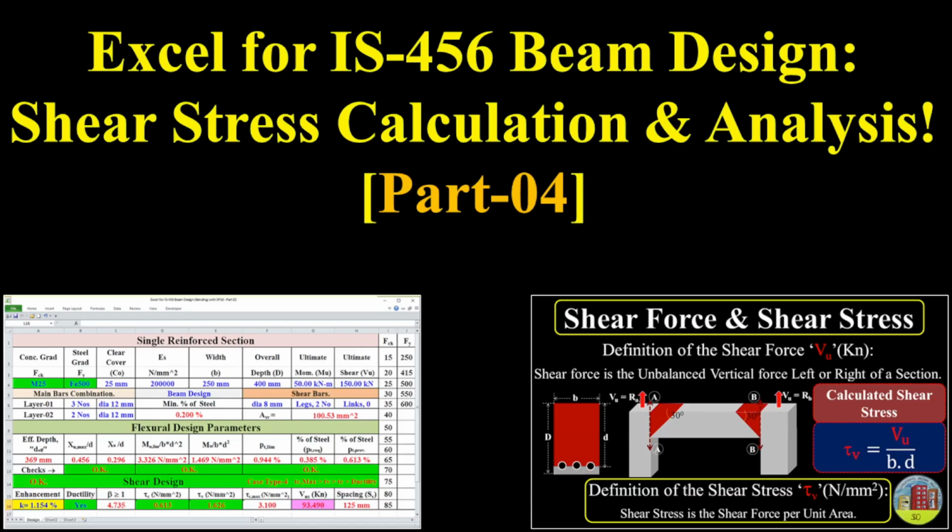We'll cover calculating design shear stress, tau V, nominal shear stress, tau C, maximum permissible shear stress, tau C max, and how to determine shear reinforcement, or stirrup requirements, using our Excel spreadsheet.